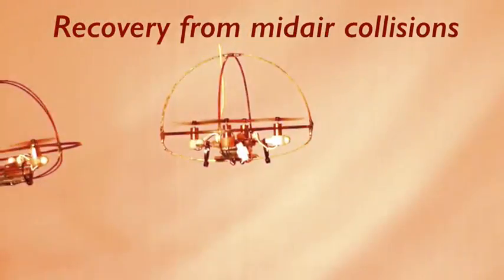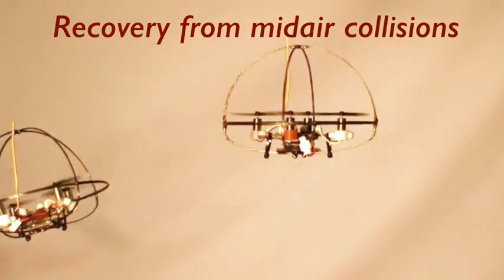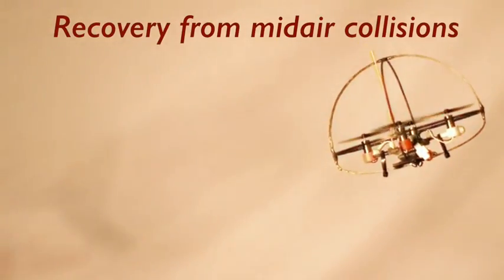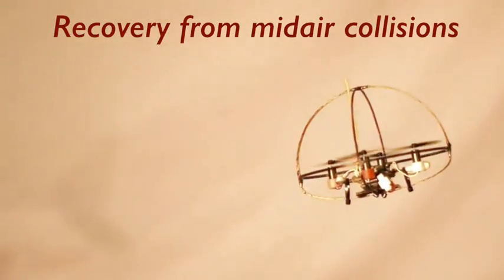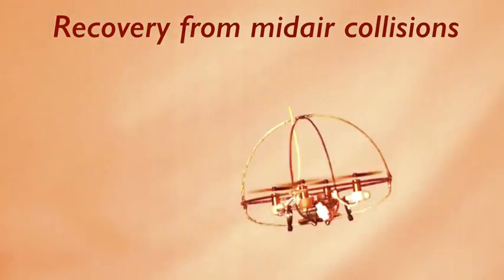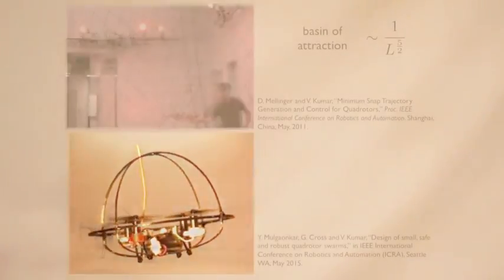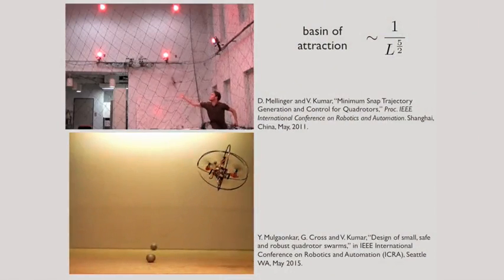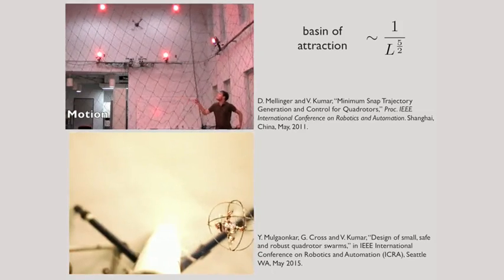You can see the advantage of small size in this video clip, where these two vehicles are commanded at a relative speed of 2 meters per second to collide, and they're able to recover from the collision. Again, it's because of this large basin of attraction for the nonlinear controller that the vehicles are robust to perturbations like the ones you see here. In fact, the size of this basin of attraction scales as 1 over L to the power of 5 over 2. Again, the smaller the characteristic length L, the bigger the basin of attraction.